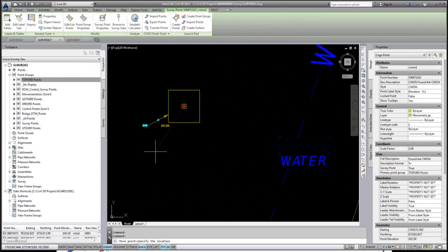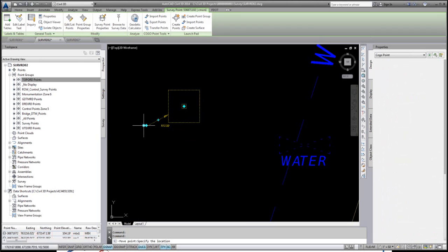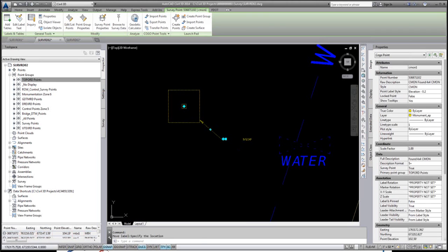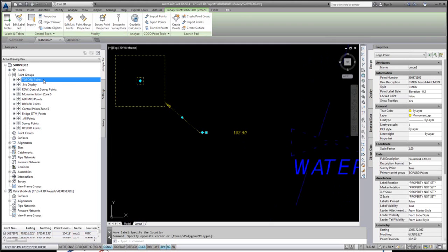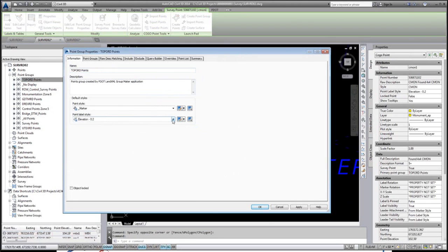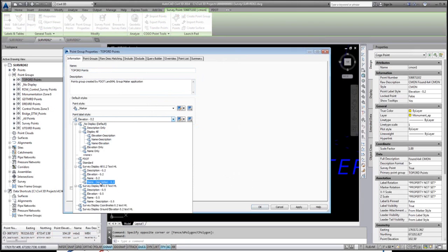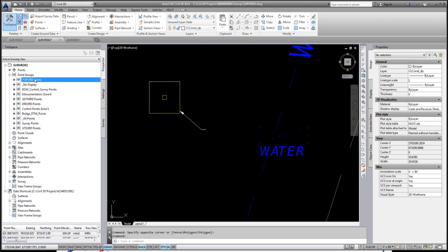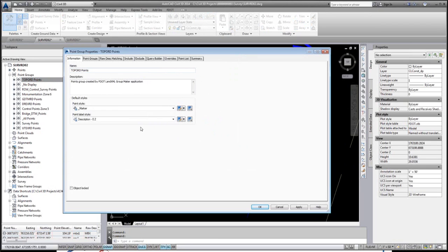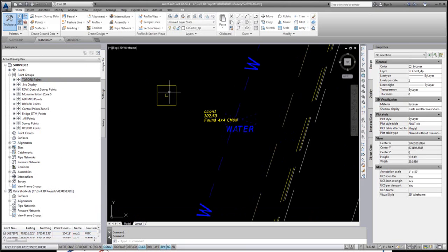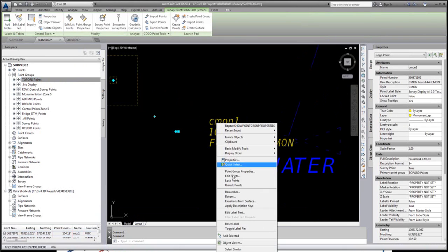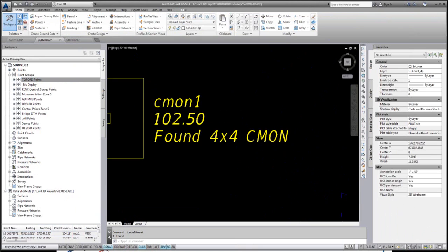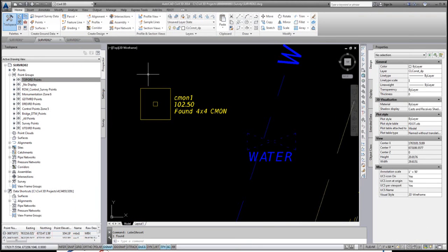What I want to show is that I can move these labels, in this case just an elevation. If I want to change that to say just a description, I would do that here. If there is a description, it will show. If I want to show everything and have it associated to 0.05, I would choose a label here. So okay. Again, it's off to the side. I can reset that label by saying reset, and you'll see the stacked version of this particular label.